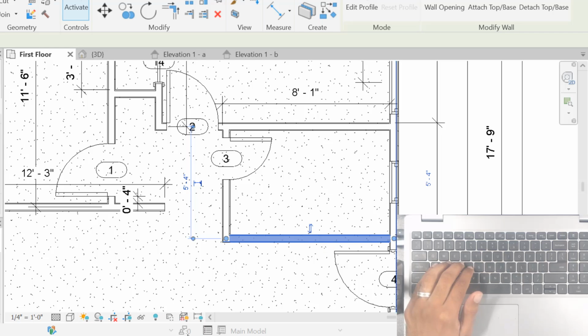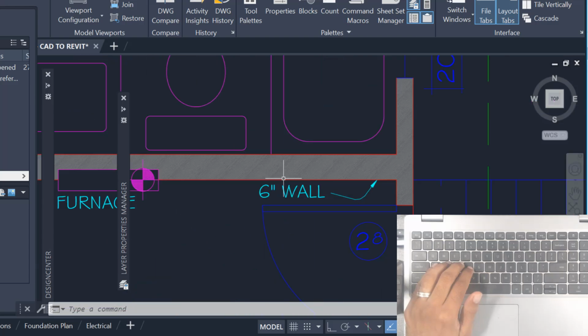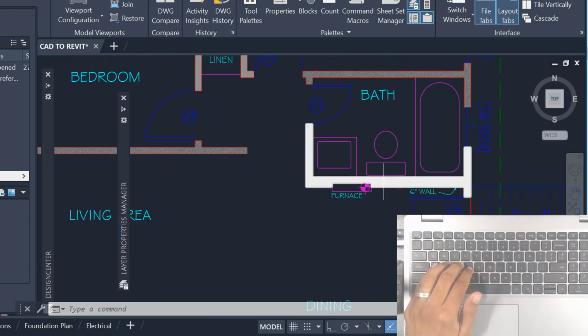According to the actual drawings that we have, this is our plumbing wall. And if this is our plumbing wall, it's a 2x6 because we need to have a toilet drain that runs through here, which is a 4-inch diameter pipe or 3.5-inch depending on how your domestic is wired. So you have a drain pipe for your bathroom, a drain pipe for your bathtub, and a drain pipe for your sink, along with the vent pipe that goes all the way to the ceiling.